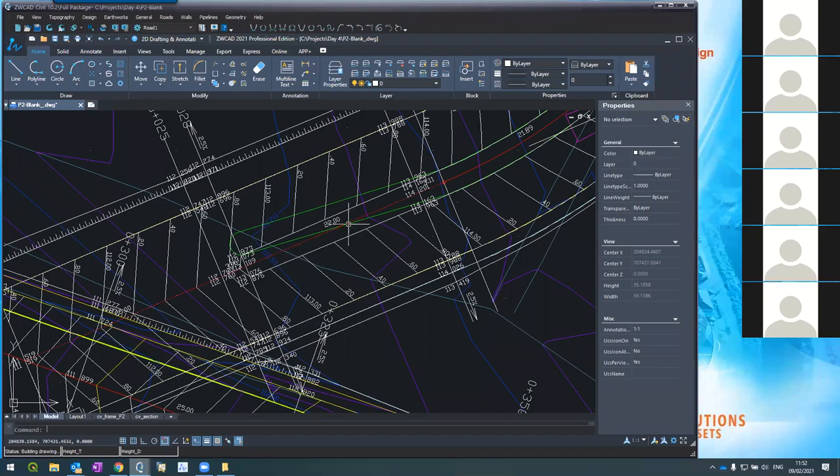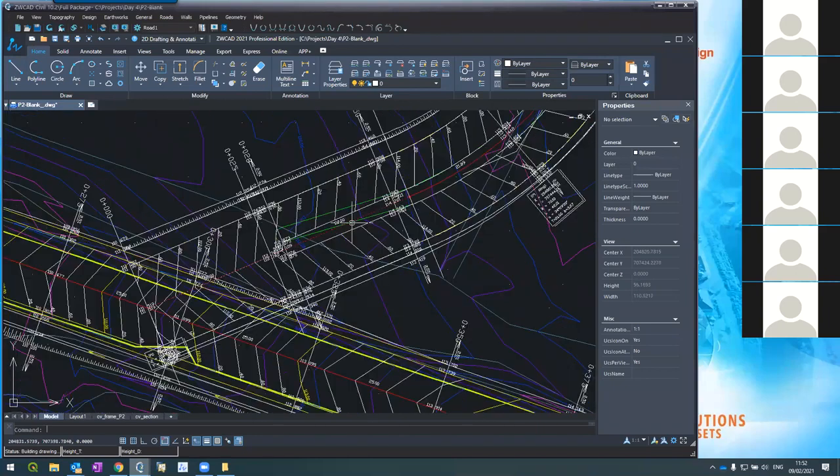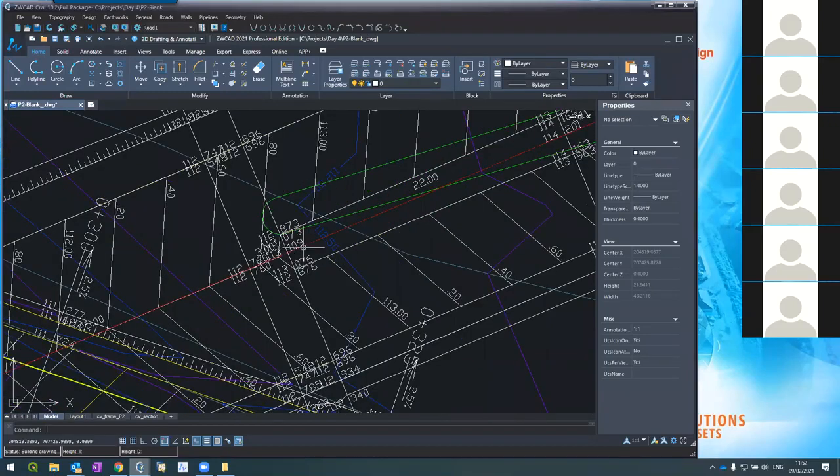But these are classic problems that we see. Many times people send us projects to review, saying, oh, I didn't get what I want, but this is the classic problem. The typicals in the extract are not suited to the geometry, so the system doesn't know what to do. It looks from the center line for the segment called median.